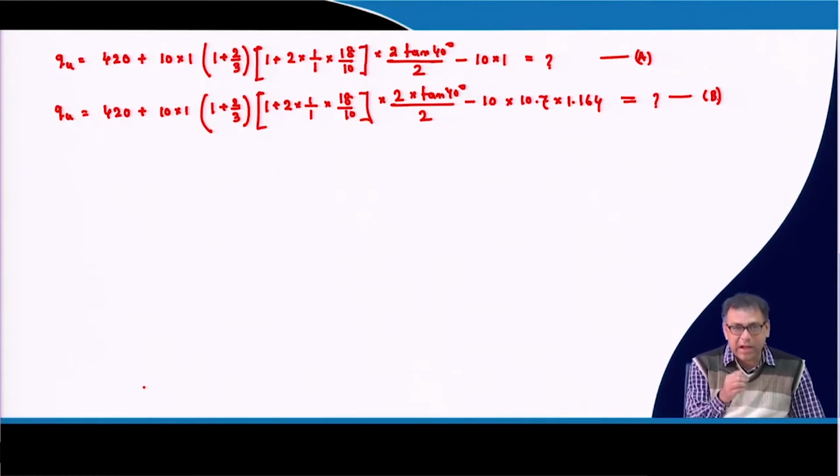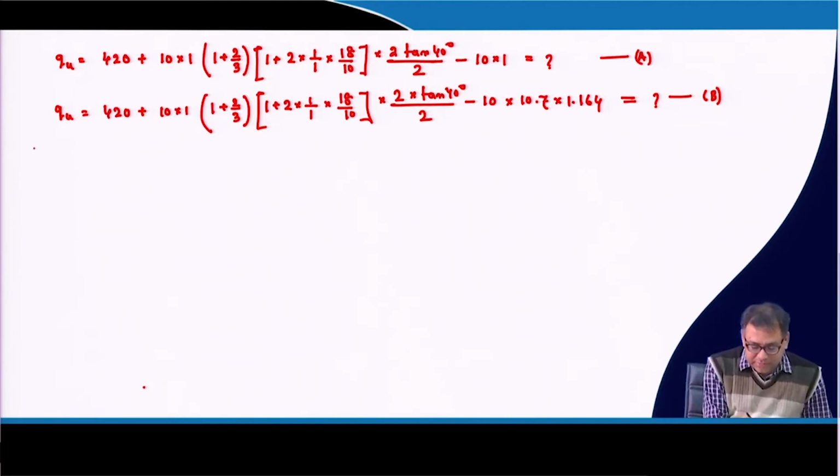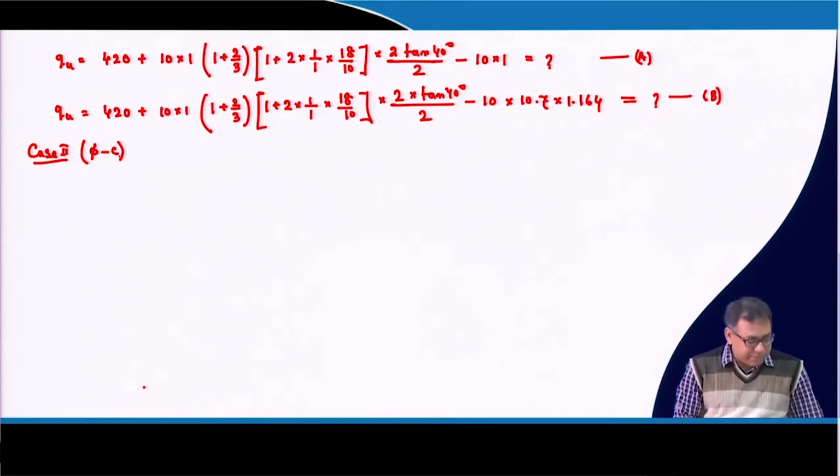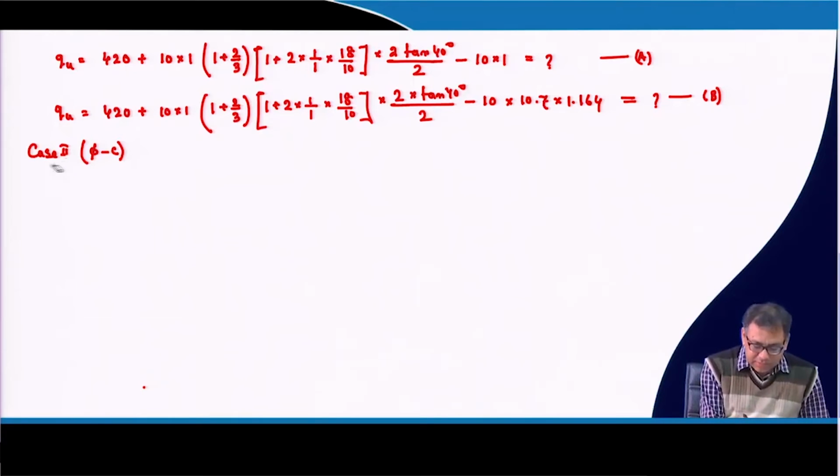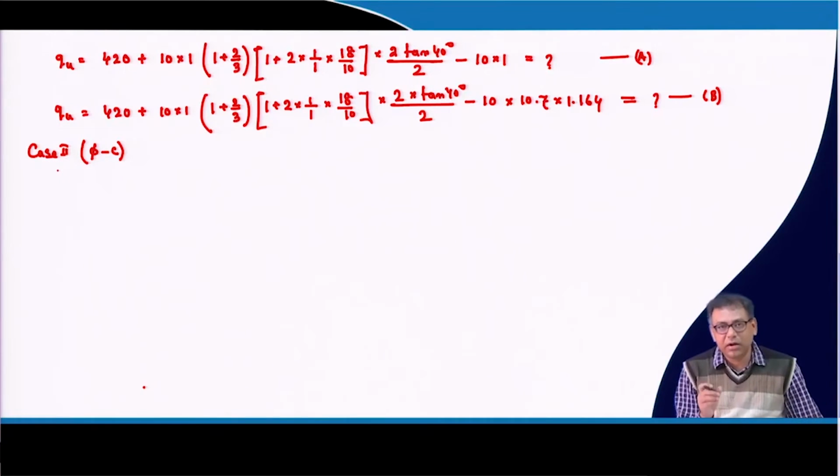Now, among these three cases that I have discussed, I am taking case 2 for this calculation, I mean for other footings, because that means your top layer is stronger sand and the bottom layer is weaker clay, and the properties are same. Position of the water table is also at the base of the foundation, dimension of the foundation will now change.